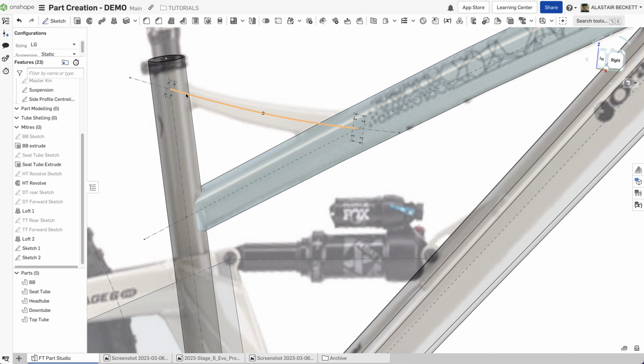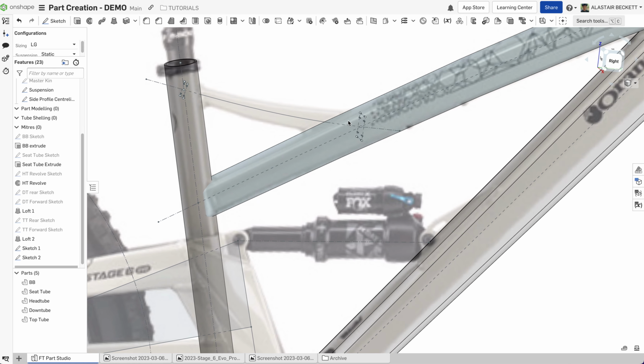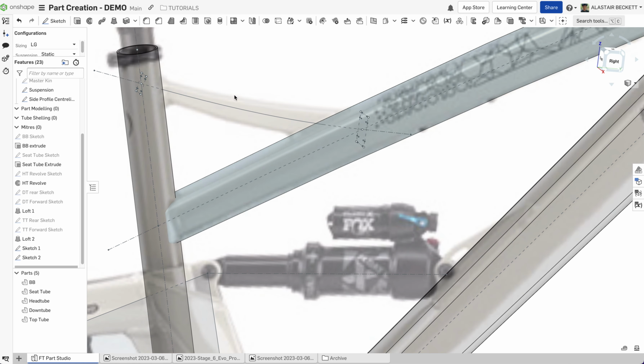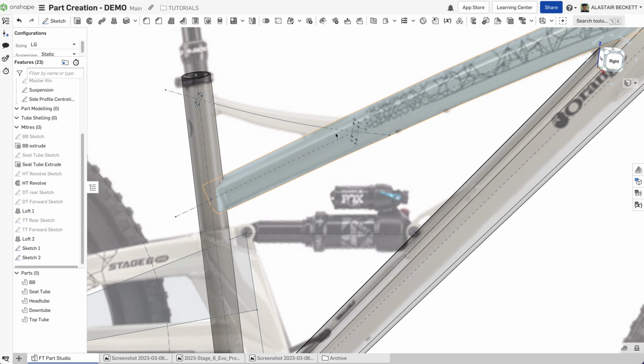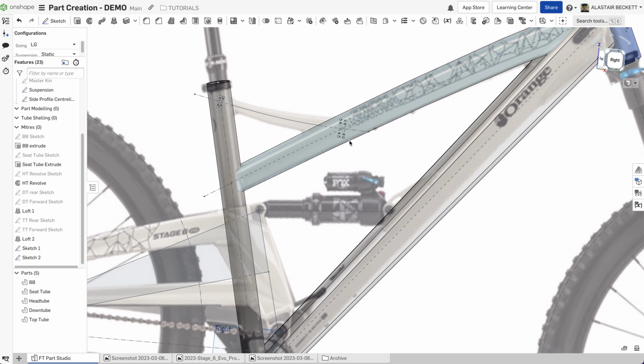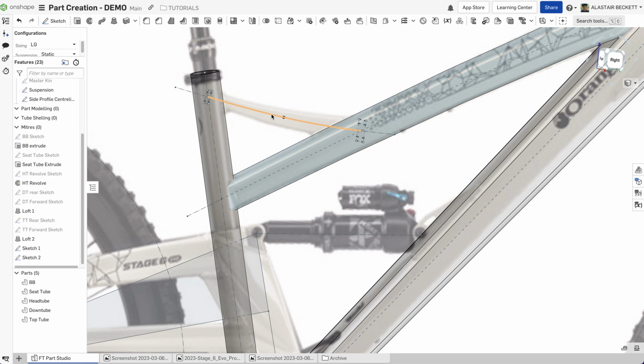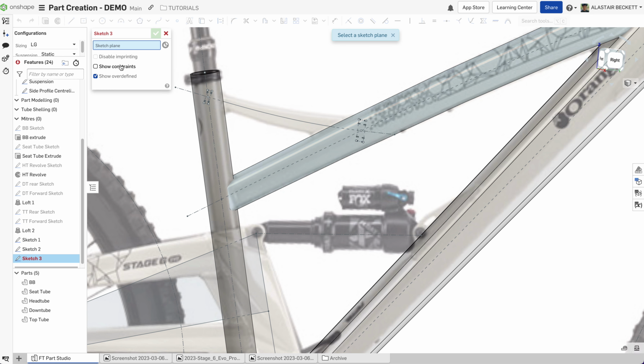Okay, so we could just loft with the center line if we wanted to, but maybe we want a slightly different curve on the top than we do on the bottom, or we lose control. If you're relying on the center line, really you are only determining the path of where the loft is going to go. You may decide that you want it to start thinner and stay thinner for longer, and you can't really control that as easily. So what we do then is we use guide curves.